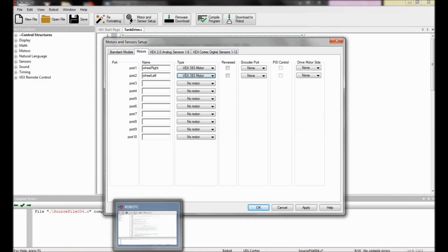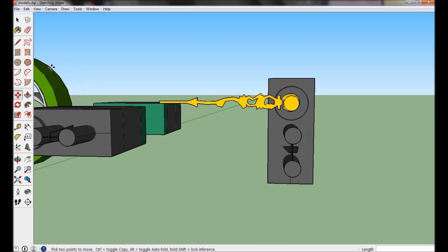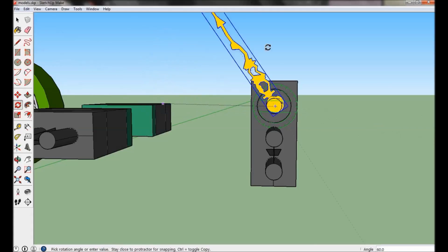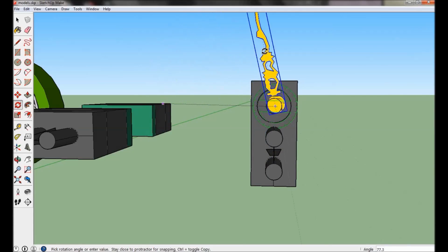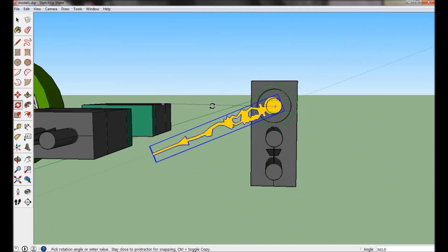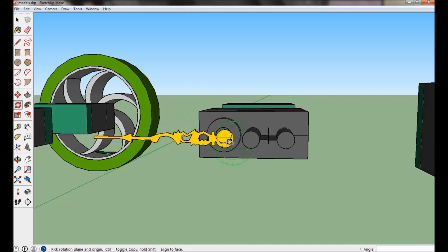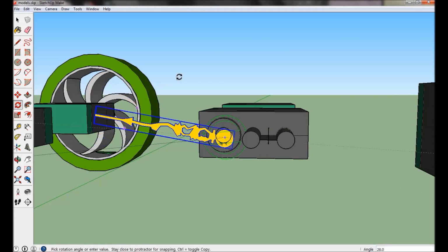Okay, so when you have a motor in Vex, they get values that are between negative 127 and positive 127, where 0 means that there's no movement in the motors, right? So when we send positive values to the motor, we find out that they move in a clockwise direction, right? So if we said positive 50, for instance, it would send this in the clockwise position. Similarly, if we were to tip it over and run the same thing, we would see that it rotates the same way, where this is clockwise.